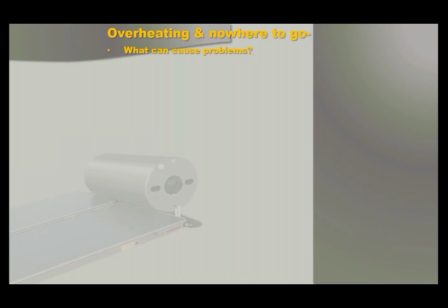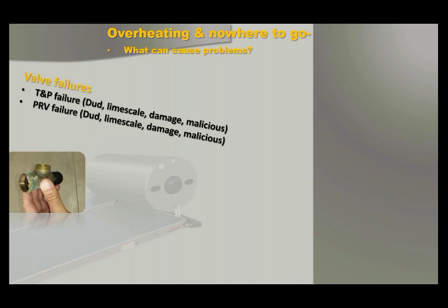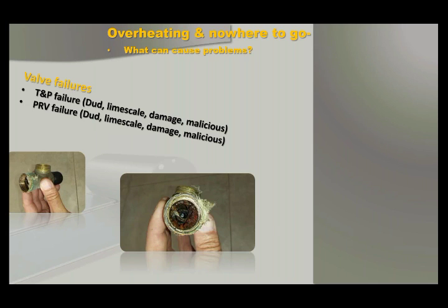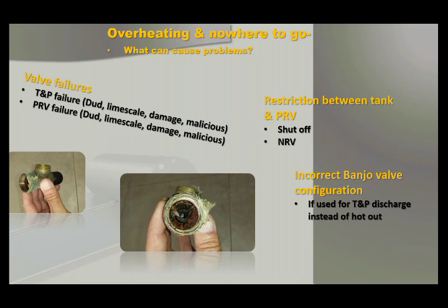Things go wrong, and we've got to make sure that when they do go wrong, we've catered for it, and we've looked at it, and it's handled, as far as is possible. I mean, we can't prevent everything from happening, but these sort of things do happen. And the more we realize that it is, in fact, a very real possibility that as we walk away from a site this evening at 5 o'clock, by 8 o'clock this evening, we could have a catastrophe on our hands because we didn't do this, or I didn't have a TP valve in my toolbox, or shut it down, don't even commission it.